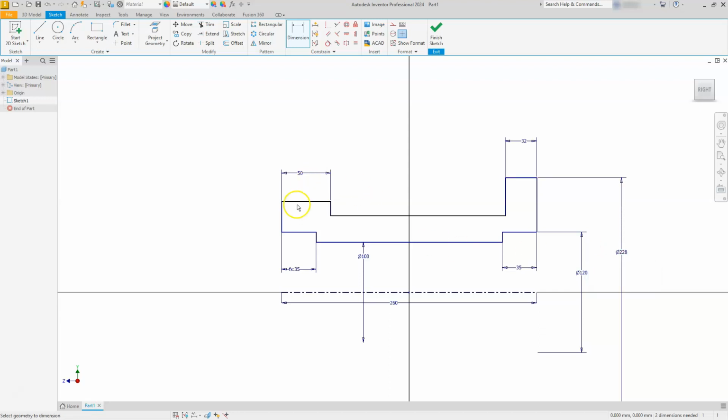This front one has a diameter of 90. Well, sorry, it has a radius of 90, so that means the diameter is going to be 180. I also have a diameter going through the middle here. That's sitting at 140. And now if I look down, I should see that it is fully constrained.